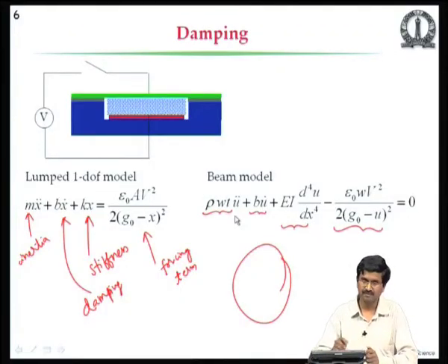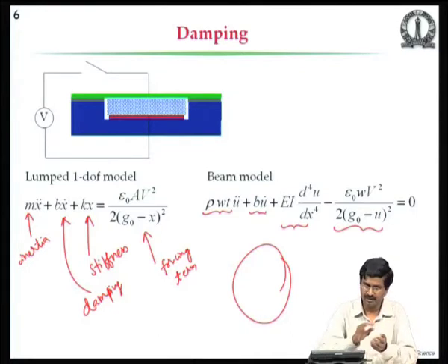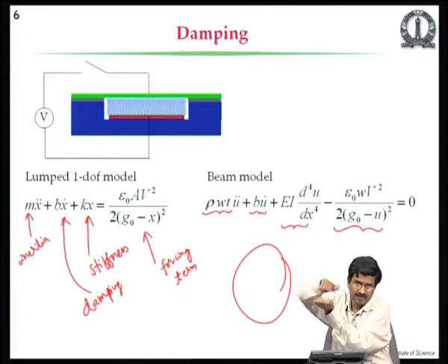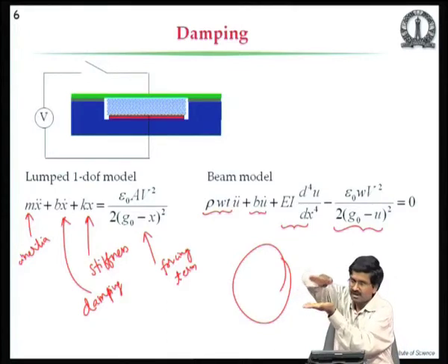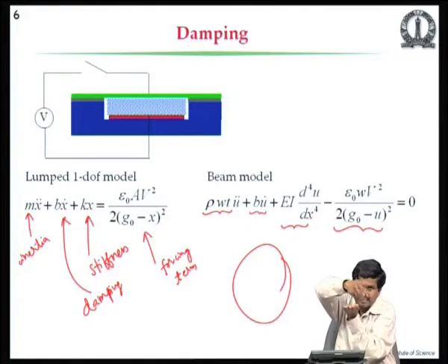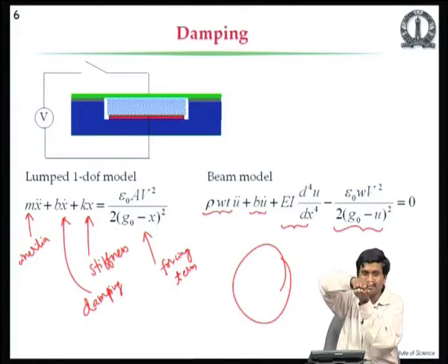First, we said if the plate is moving like it happens in an accelerometer proof mass moving over the air film, then you have the Couette flow condition. But there is another case where the Z-axis accelerometer can move up and down like this. There is a bottom substrate, the other one goes up and down, then the air here gets squeezed as the plate is moving. It is squeezed and it can move out from the sides, because you have the finite size of a plate. When it moves like this, all the air that is here can escape from the sides, but there will be different effects based on whether I am doing it slowly or fast.